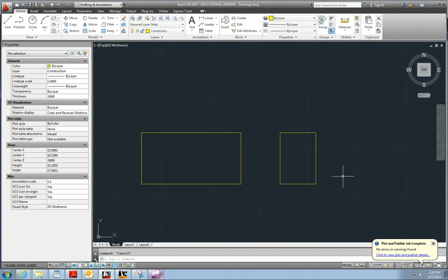Alright, let me do some offset. So offset 1.38, and then I think that's the only offset we're going to be able to do from the front view. And let me offset from the bottom 0.5 in the right side view. Okay, let me go to my visible layer, and I think I'm just looking at it. I'm going to work on the right side view first. I think that's what I need to do.